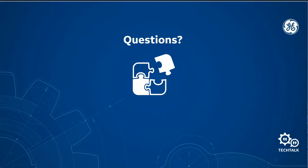Here's a great comment. Each of the situations presented could have been solved at the time of testing prior to putting the equipment in service. I agree. The comment brings up a really good point, that testing the devices is very important. But in most of these instances, it's not even a case of testing in the traditional way, where you have a test set and you're injecting quantities. It's more of a commissioning service type testing. If the tester had looked at the quantities available as metering quantities on the relays, then he could have discovered that he had errors and resolved them before it caused a trip or before it was put into service.